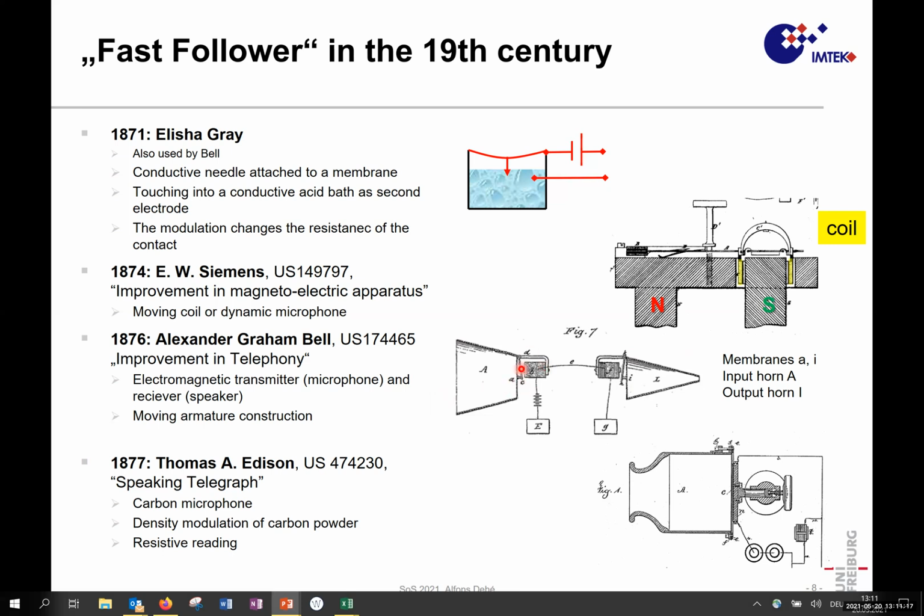So basically there's an electromagnetic coil, and a yoke is moved against this and modulating the current. And the inverse, because it is of course inverse, is on the speaker side, and you put this to your ear, and then you hear the sound, the mechanical movement of this diaphragm, which is transferred via the wires. So again, the balanced armature device is still nowadays in hearing aids, for example.